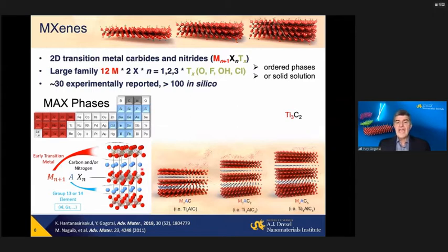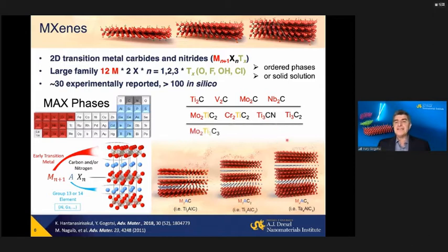So we have to etch the monatomic layer out of the ceramics to break apart the structure. Then we can produce Ti3C2, which was the first one, but also many other carbides and nitrides. Since they now have a transition metal on the surface and aluminum, say, or silicon or another element is etched away, the transition metal won't remain unterminated.